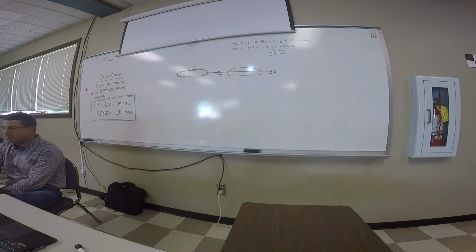If you're shooting anything that is on the surface of pavement, and you get something that's in the pavement, and you want to identify it, you're going to shoot it on the ground, and we can use it for topo. PS dash what you think that thing is, and maybe say CPIC. You can throw descriptors on the ends of those single ground shots, concrete shots, pavement shots.